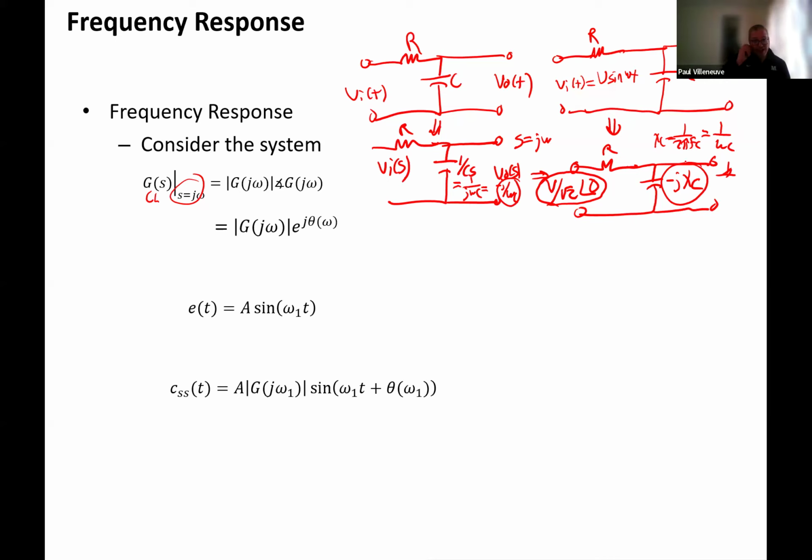So going all the way back to your AC circuit analysis, we have been doing for a lengthy period of time the conversion of the Laplace domain circuit into complex frequency representation. And we can extend that to do Bode plots, because the difference about doing AC steady state circuit analysis is that we're using one frequency. Typically in North America, it's 60 hertz. Whereas when we're doing Bode plot analysis, we are allowing the frequency to change pretty much anywhere we want it to be. And including, we can also do a really basic one in DC.